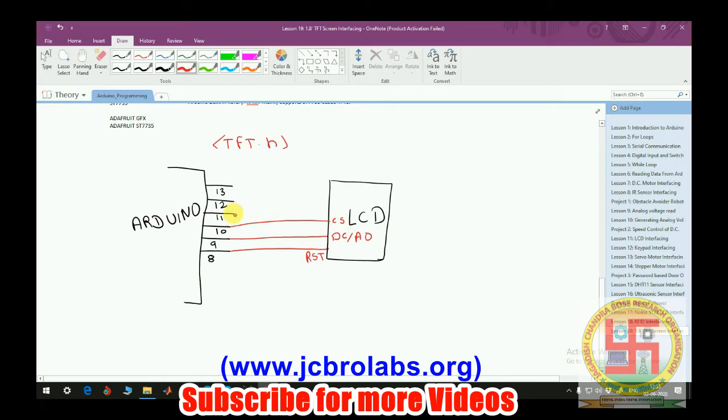Pin number 11 is the MOSI pin, so it is connected to the SDA pin on this LCD, and then pin number 13 is connected to the SCLK.